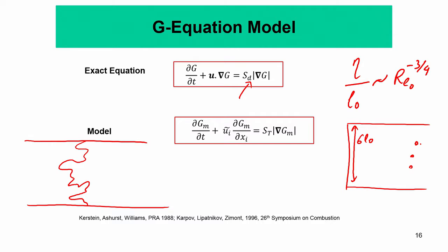So if you have to reduce your smallest scale by 10 times, so your delta is now 1/10 of the previous delta, what happens is that your actual grid size, or the number of grid points, increases by 10 to the power 3, not just by 10, if you assume it is a cubic domain, depending on the domain size or shape, of course. It grows in a cubic manner. So that produces immense computational load, which is really not possible.